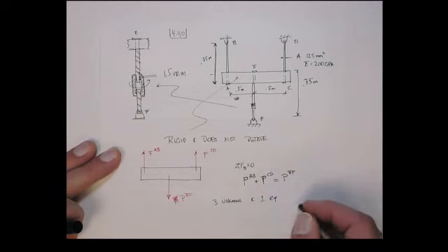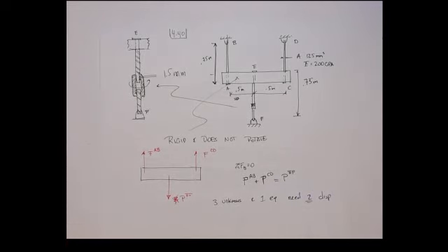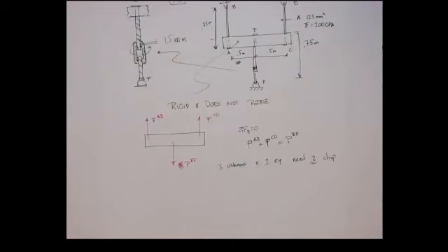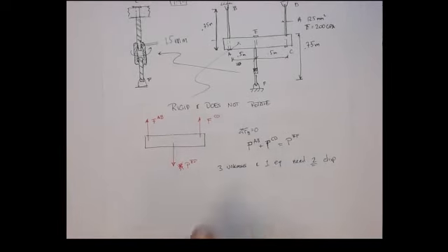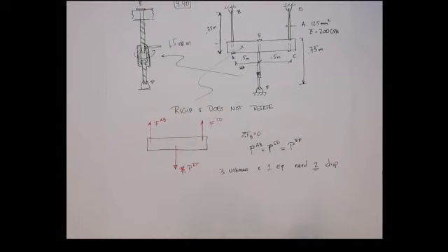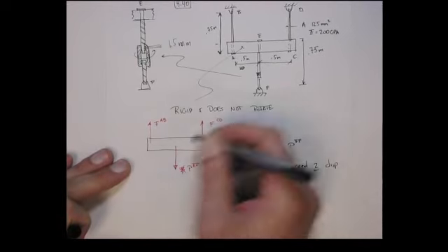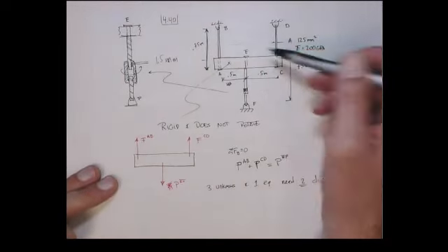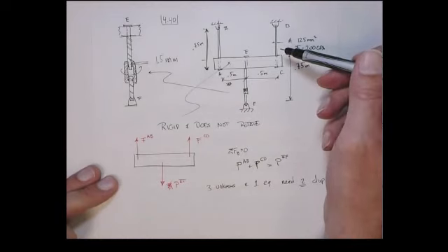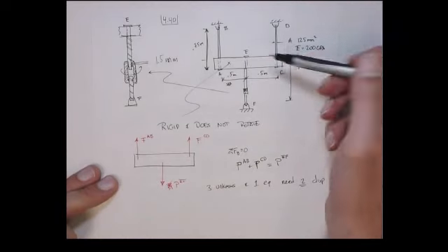So that means we need two displacement conditions, two compatibility equations. Now what can we do here? All right. Well, one of them is easy. One we can get from the fact that it doesn't rotate. And if we consider the fact that it doesn't rotate, then that tells me that the elongation of this element has to equal the elongation of this element. That's obvious just from symmetry.